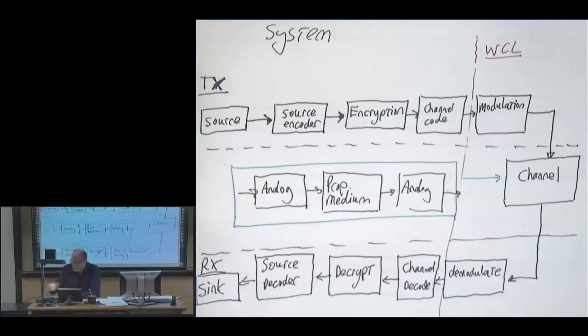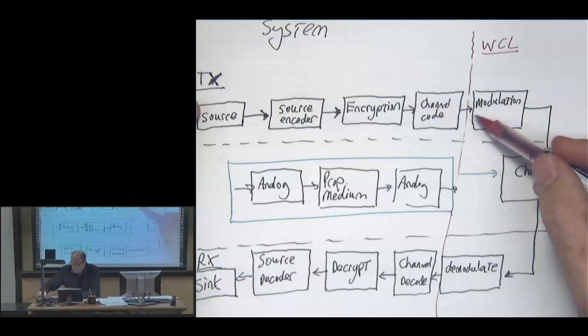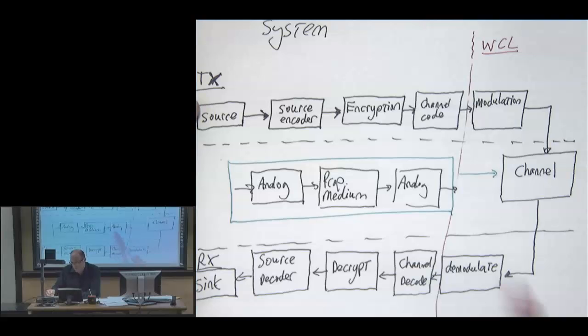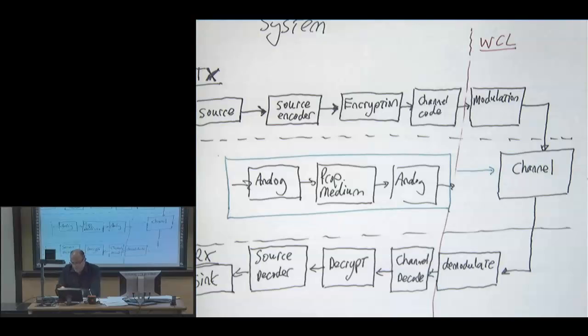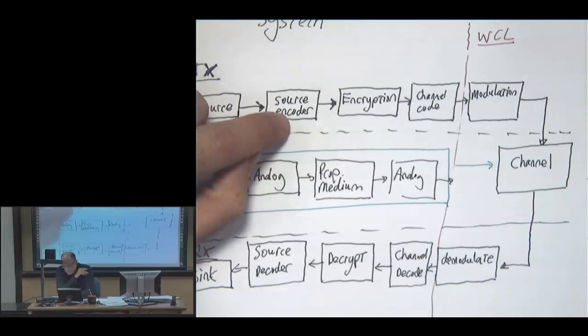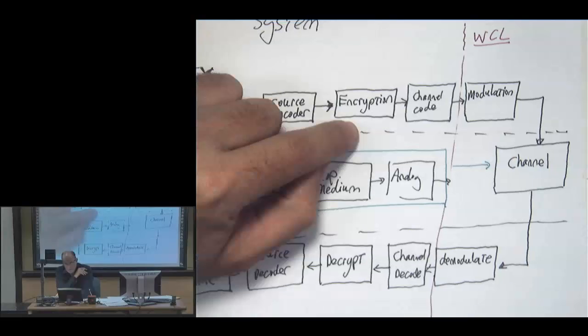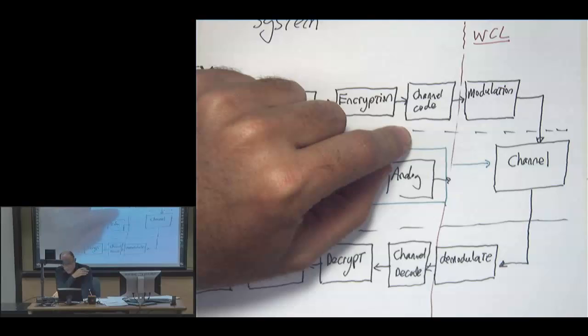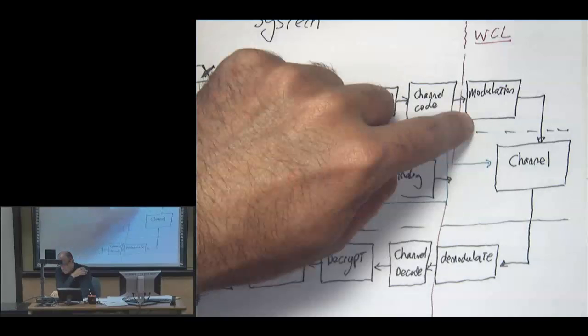And in the lab, you're going to focus primarily on transmitting uncoded information over the communication channel. So we have some coding in the lab, but we just tend to not do it. We don't do any encryption. We don't do any compression. But the way these things are here, again, this is source, compress as much as possible, add possibly encryption. This is where we're implementing some security, add redundancy to correct errors, and then modulate, just convert these bits into some kind of an analog waveform.